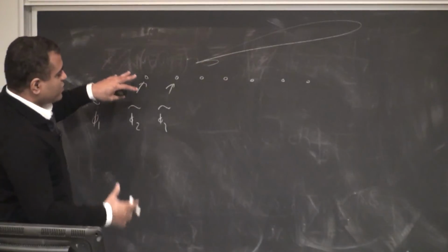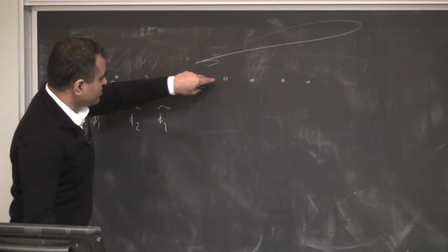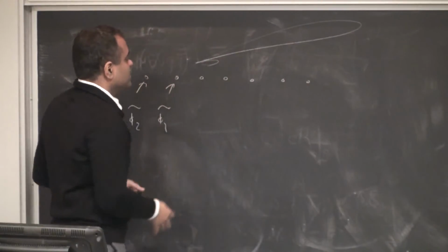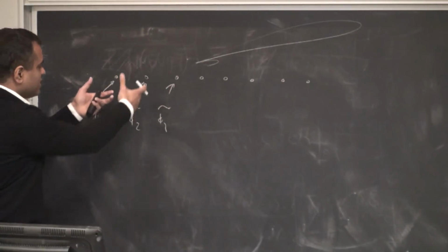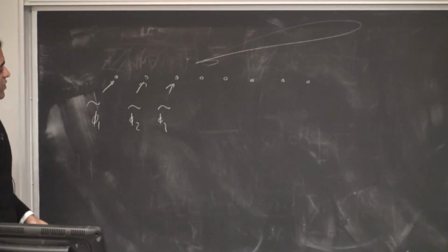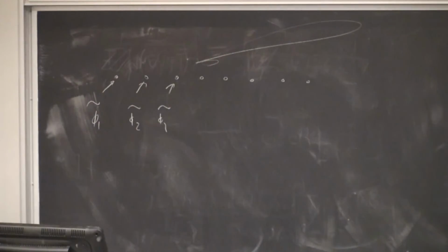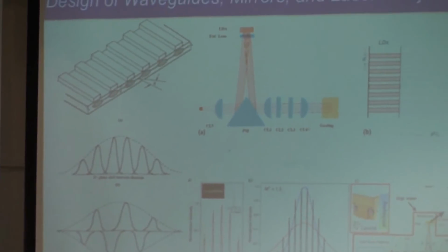These are in a microwave domain where you have individual metal arrays of antennas. Sometimes these days transistors are used here for transistor microwave amplifiers, and you can create radar arrays like that. But for lasers, it's slightly different because the photons here need to become coherent with the photons there, and that's not a trivial task.